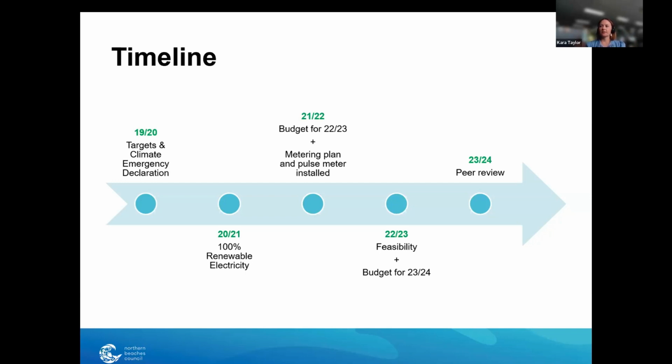The report also gave us the relationship between energy intensity and pool area. Apparently, we're lucky, we're winners. We've got a really high pool surface area to gross floor area, which I don't think is what you want because that means our energy use is really high, but yay us. We also included the energy consumption breakdown. So that's basically so that we know what's using the energy where, how much is going to pool heating, how much is going to domestic water, how much is going to pumps, AC, etc.